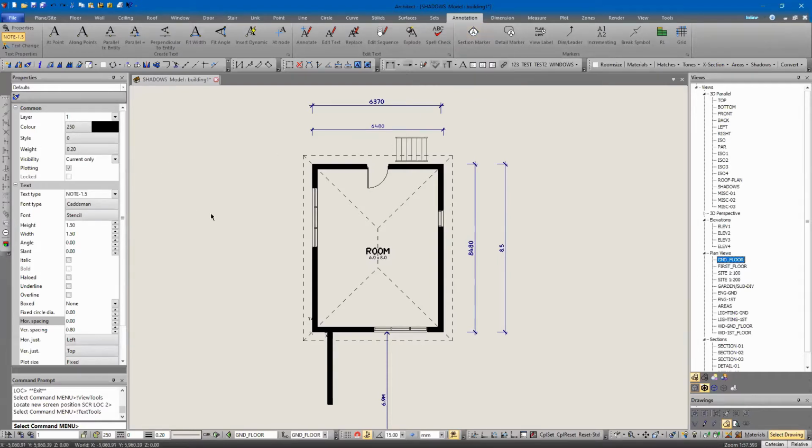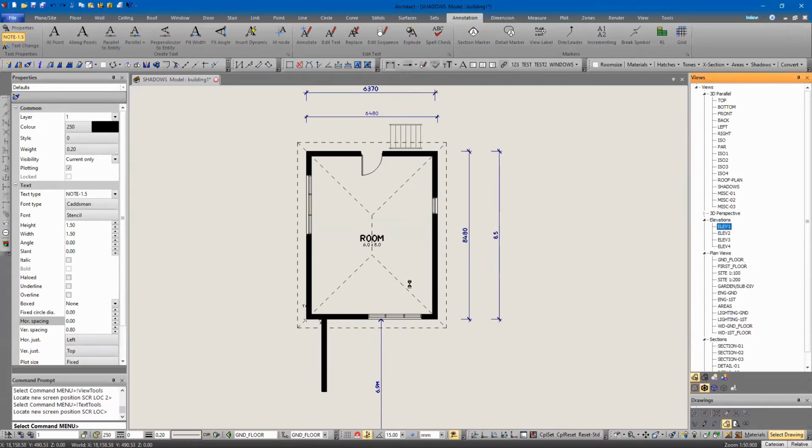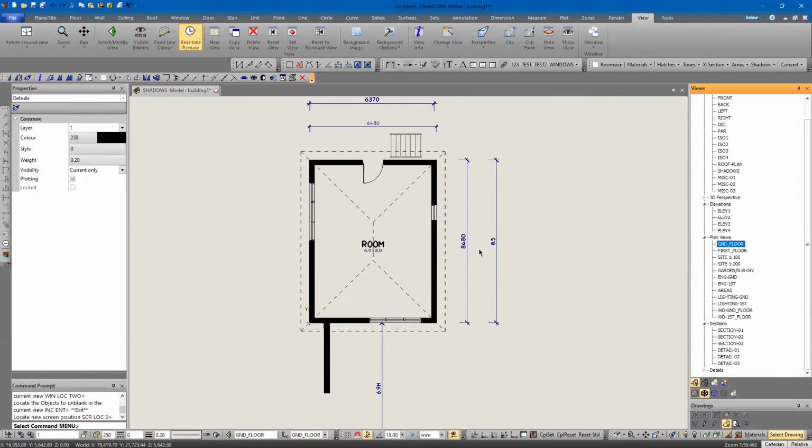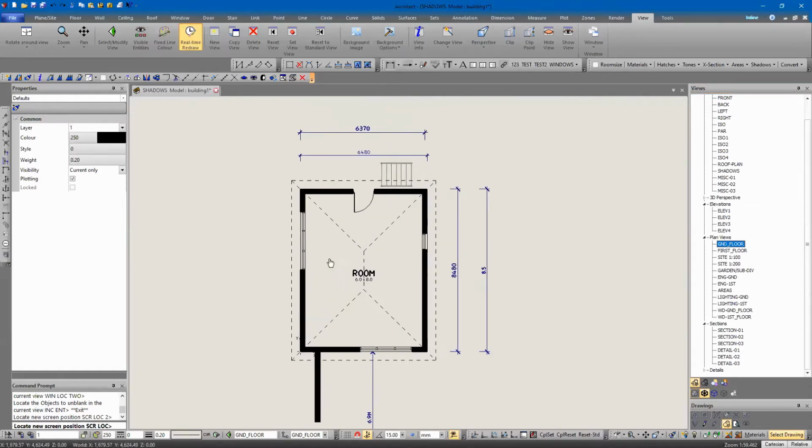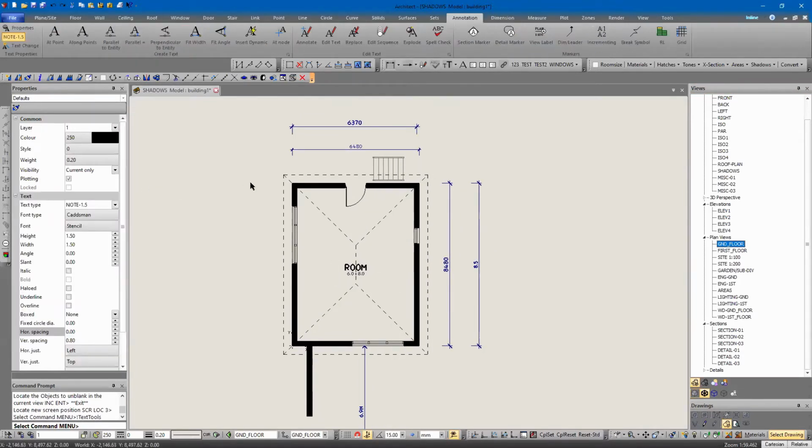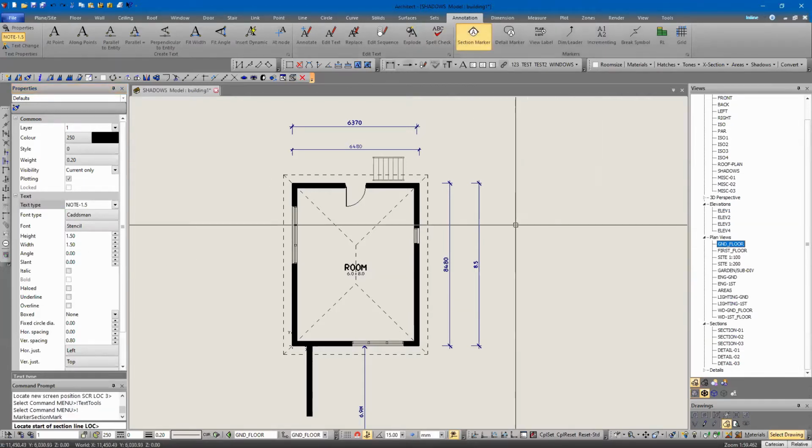what you first need to do is, if you've got stories that you're using, if I go to ground floor, make sure that my fonts are set, because when I create a new view, it'll create new story markers, and making those story markers, it adopts the current font settings. So if you have that set to TrueType fonts, it then gets very lost and doesn't put any fonts on your story markers. So set it how you want, then go to your section marker.